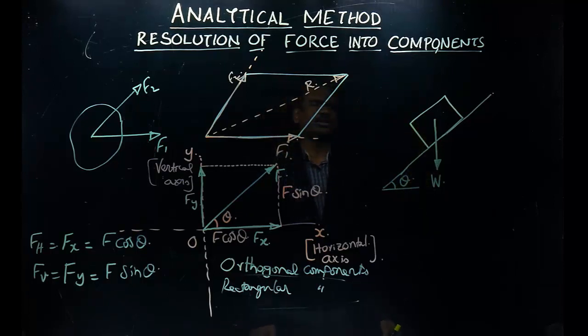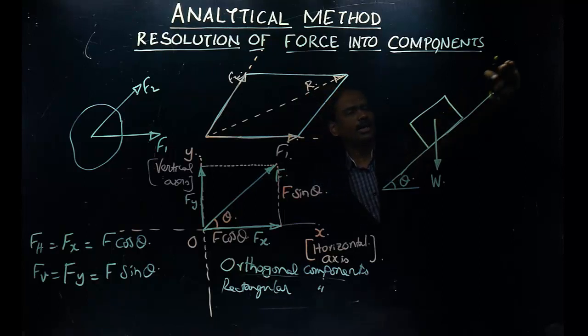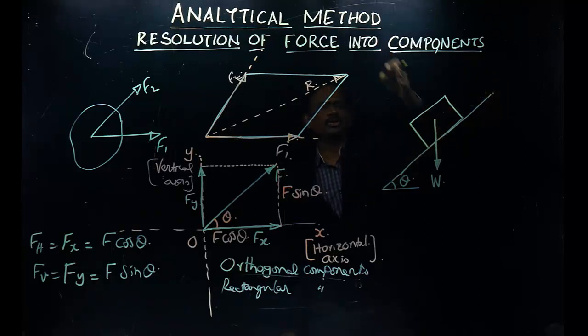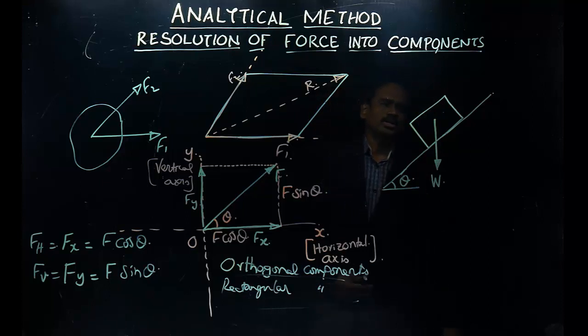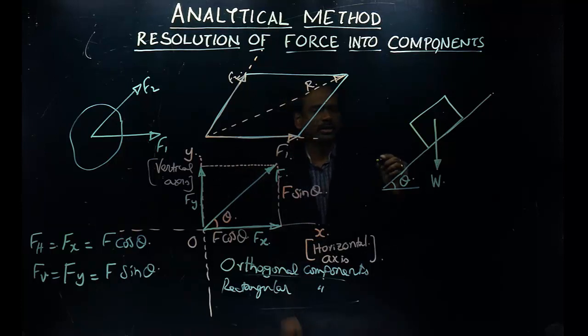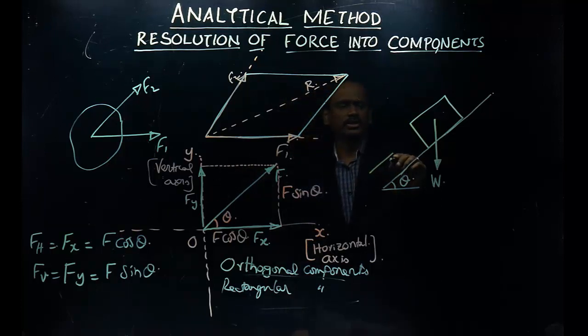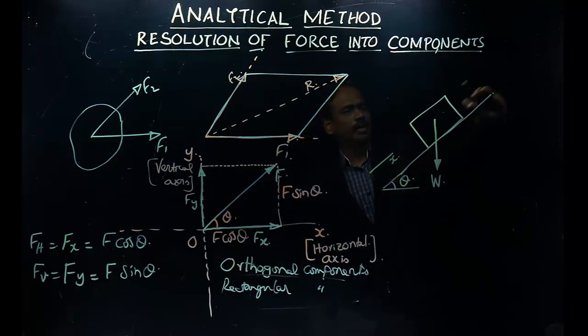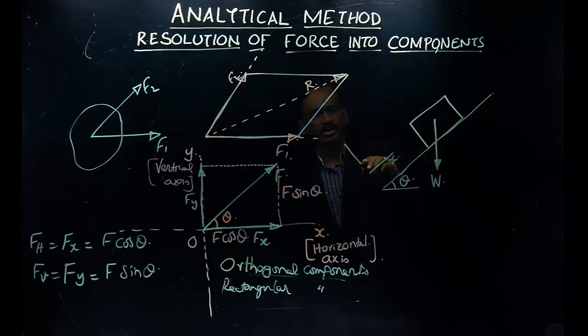We have to resolve this force along the axis parallel to this plane and perpendicular to this plane. In such cases, we can choose the axes as per our convenience. It will not always be horizontal and vertical, so it is better to call these axes x and y. Right now we can fix the x-axis parallel to the plane and the y-axis perpendicular to the plane.